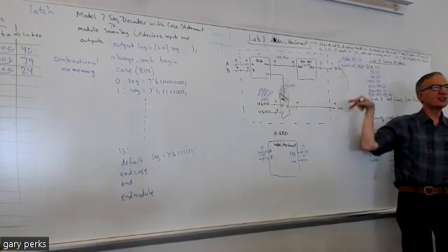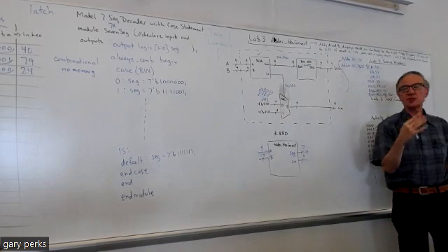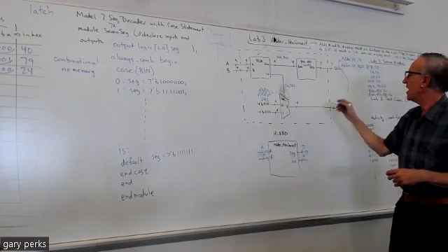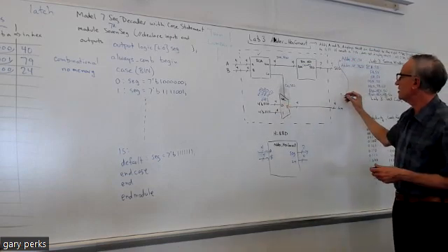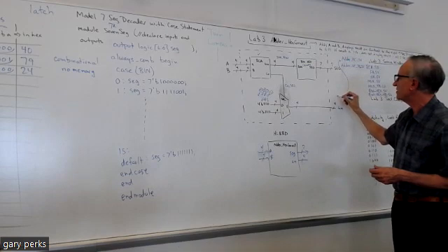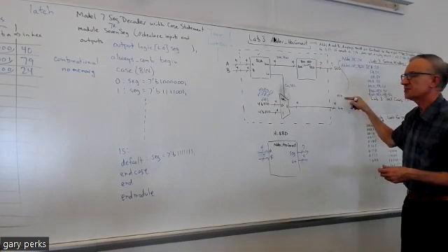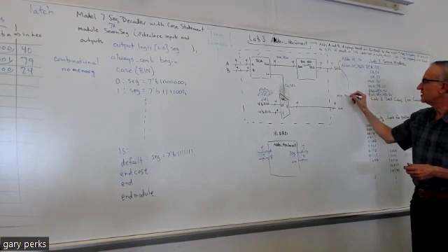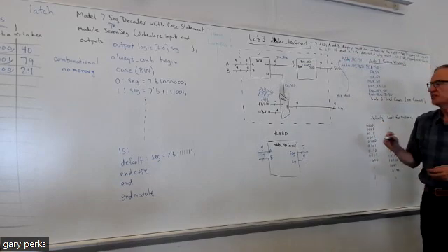and you're making all the other connections. So in your structural model, connecting them all together, let's say you call your mux file mux. So you'd have the file name, and then the next thing is the label. Maybe you call it mux 0.